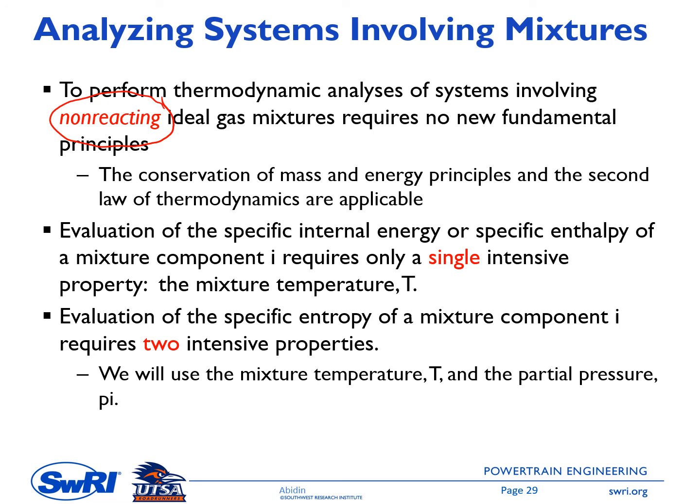Evaluation of the specific entropy of a mixture component i requires two intensive properties, as I did mention in the previous slide. In this case, we will use the mixture temperature T and the partial pressure p_i to determine, for example, the specific entropy of component i.